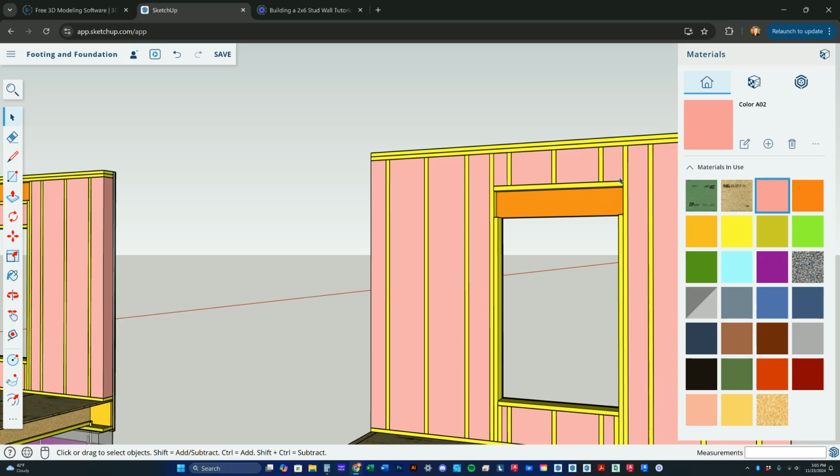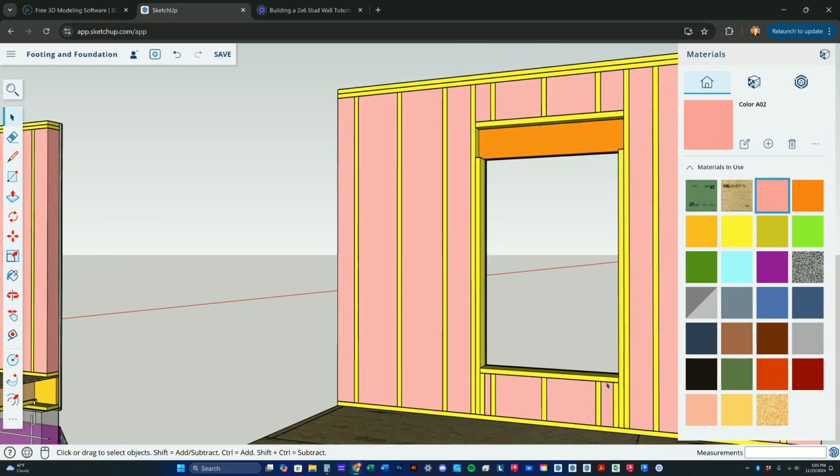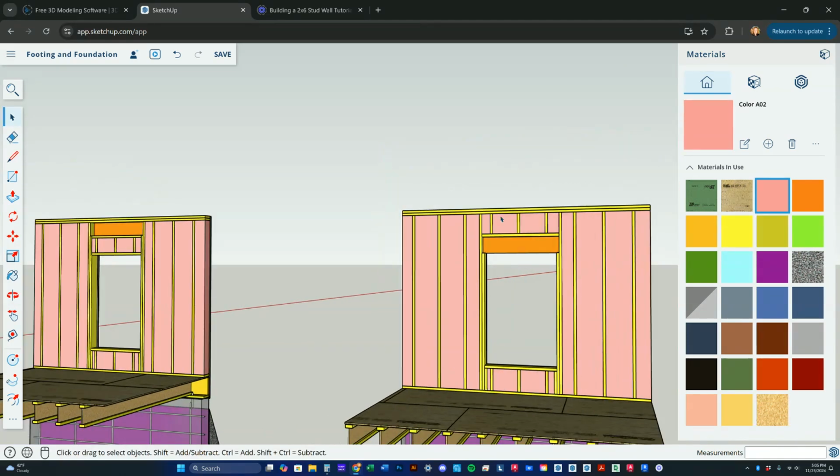And then they will put a little cripple wall above it to the double top plate and the supported cripple studs below it. This is more typical, but you also lose some of the strength and rigidity of the wall in doing it this way.